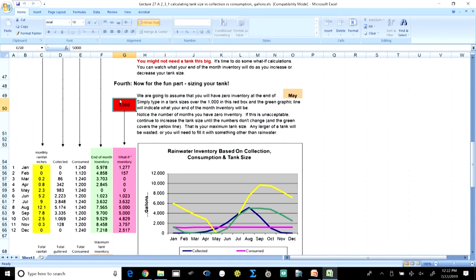Now, if I decide upon the tank size, here I have fixed it to 5000. If we have 5000, we see that almost all the volume received in each month will be stored in this. If we have a large enough tank as this, then rainwater will be sufficient to meet the demands for almost 8 months of a year. So, for 8 months only the rainwater can be used to supply for the consumption, for the demand.